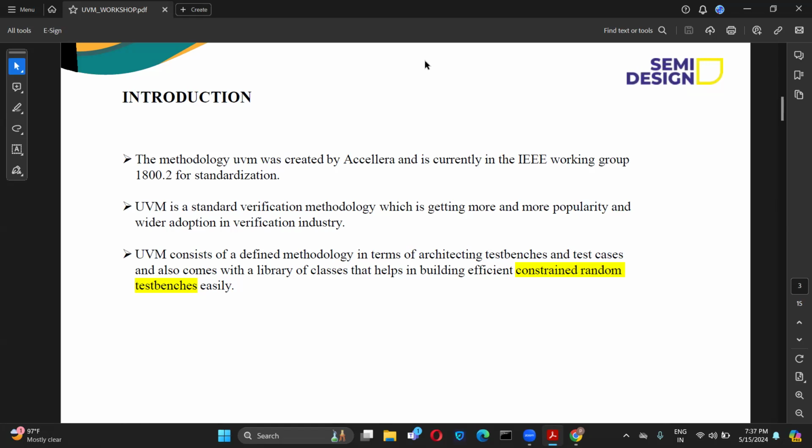So through the test bench, we give the stimulus. We write a design, and then the design is instantiated inside the test bench, and then we give the proper stimulus. We also try to observe those things in the waveforms, or otherwise we give some display statements, and try to observe what the given inputs are and what the desired output is, to see whether the output is generated properly based on our design. So these are the main things about a test bench. This is the main motto of the test bench, right?